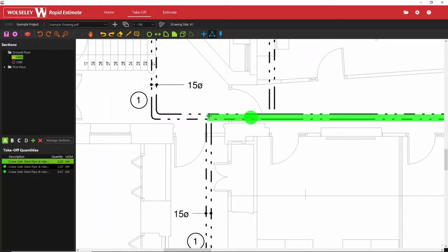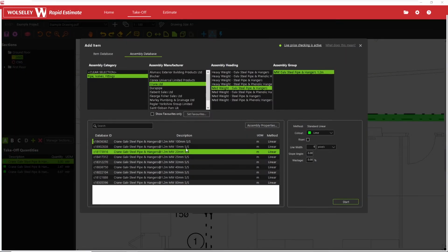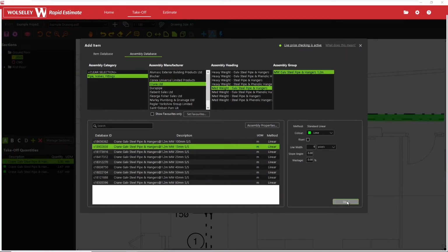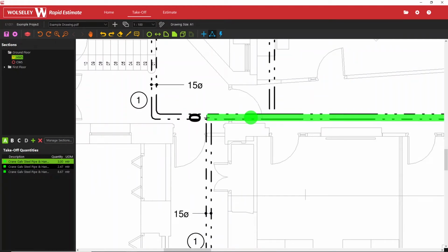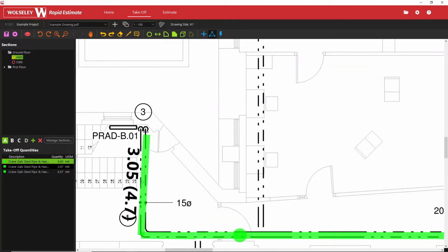So I've just right clicked in there to finalize that's where I'd like the 20mm to go. So I'm going to select the 15mm and I'm going to show you that movement tool again. So I'm going to press the start button, carry on from here. Left click from the T, left click into the bend, and then I'm going to hold my wheel down and drag myself up the screen all the way up to our rad. Left click, and now finalize that with a right click.